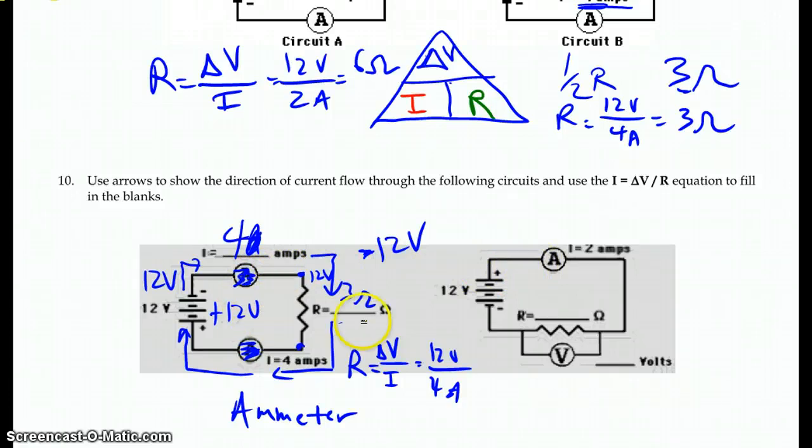It's like the wire. Another is the symbol V there. That's voltmeter. Okay, that means we're measuring the potential difference in volts. Since it's a difference, you'll notice that it has to be on 2 different places of the resistor. The ammeter is actually within the wire. It's part of the circuit. And that's because it measures current, and the current needs to flow through it. So they're actually used in exactly the opposite way.